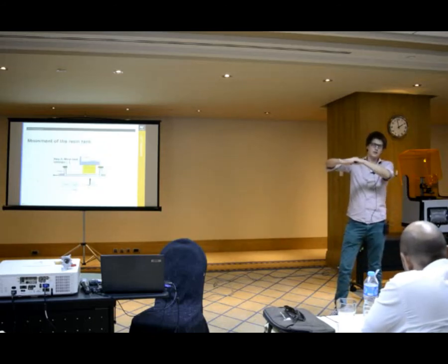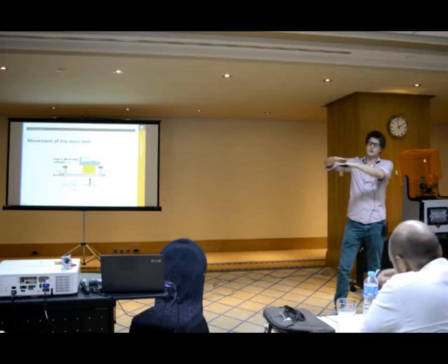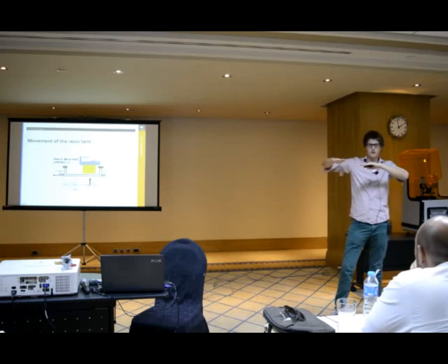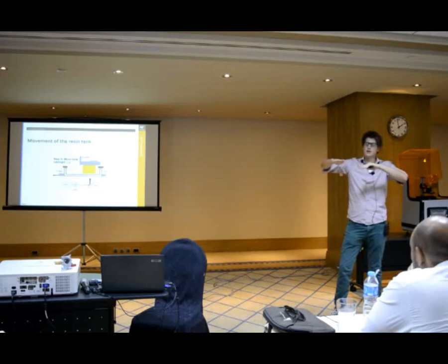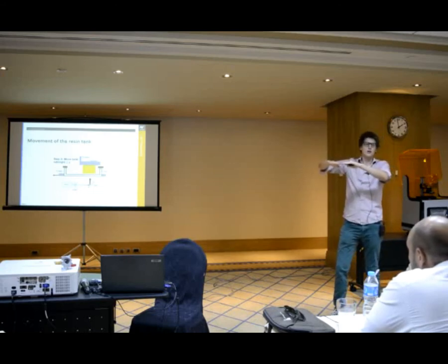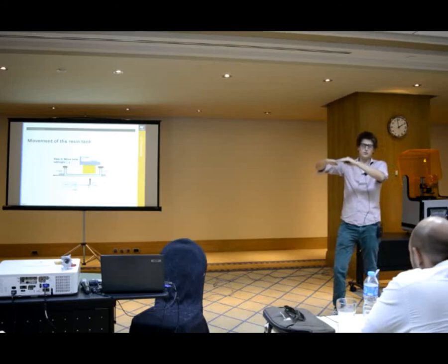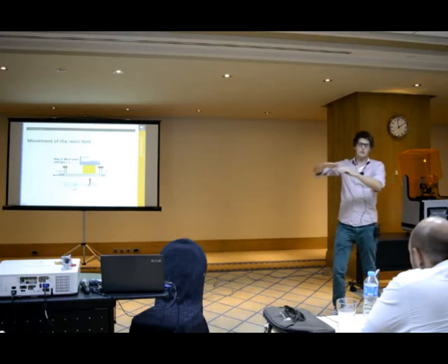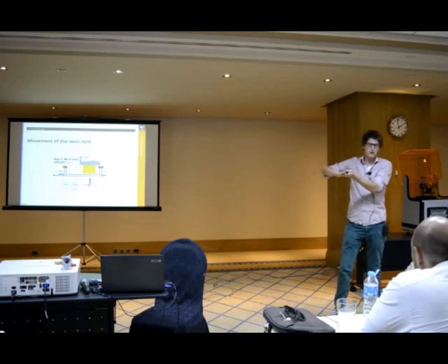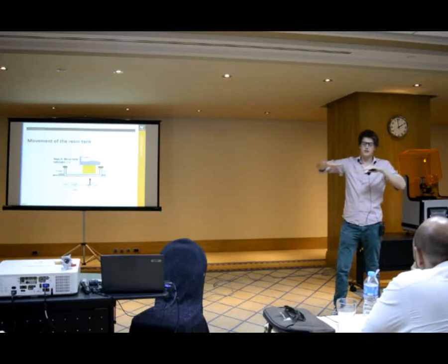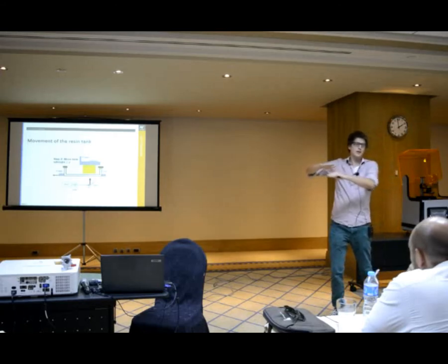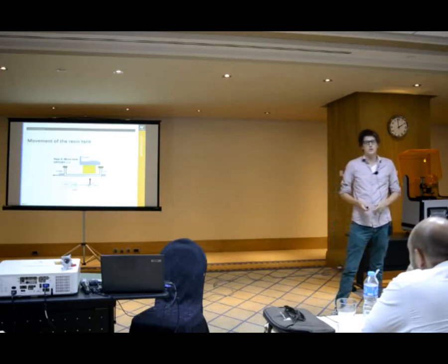So instead of pulling up the Z stage, you move your tank in the X direction. So what happens, you have your model, and you have your stage or your tank here, and you pull your tank in the sideways direction, and by applying a force in this direction, you ensure that your model will stick to the Z stage, but not to your tank, and it will not break. And then you can slowly move it up for the next layer, and you can slide back your tank again, and get ready for your next layer.